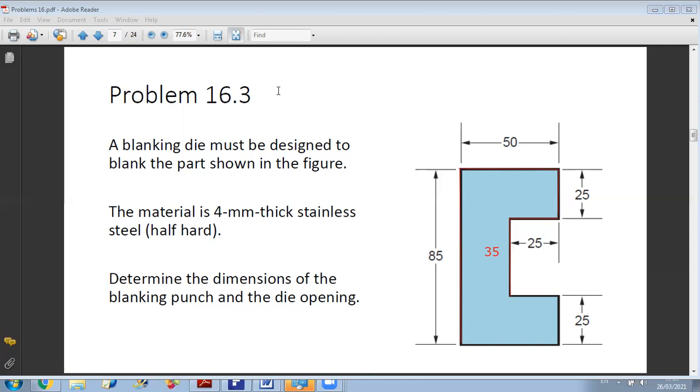Now, on the other hand, what will be the dimensions for the punch? You know that always between the punch and die you should have the clearance. If I want to illustrate the geometry of the punch, it is like this. First I should take a distance from each edge equal to the clearance. This is C from here, this is C from here, and from all sides I should have the clearance.